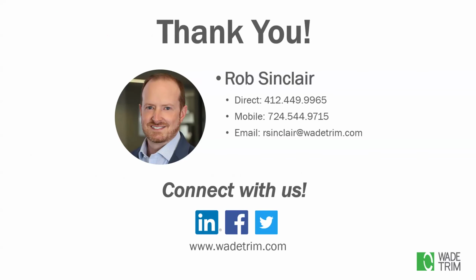We did have one question. Somebody had a large number of millions of points and wanted to know how to reduce it. I told them exactly what you were explaining, how you can reduce your points in ReCap. Yep, there are simplify tools in ReCap. There's also the simplify surface routine in Civil 3D, which doesn't always work that well. And really, when you import that point cloud, those polygon areas where you can decimate the points by area are probably the best route to go.